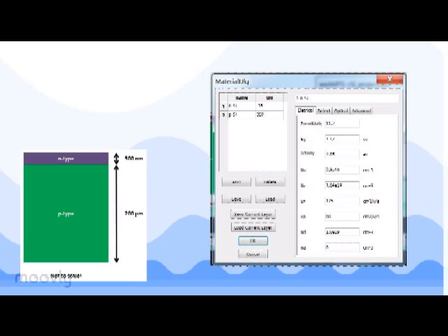The top junction is sufficiently doped to conduct away the generated carriers without resistive losses. However, excessive doping levels can reduce the material's quality, such that the carriers recombine before reaching the junction. In the base layer, a higher doping density leads to a higher open circuit voltage and lower resistance. However, if doping levels are too high, this could result in damage to the crystal. Under the optical properties, I've used data on silicon from PV Education.